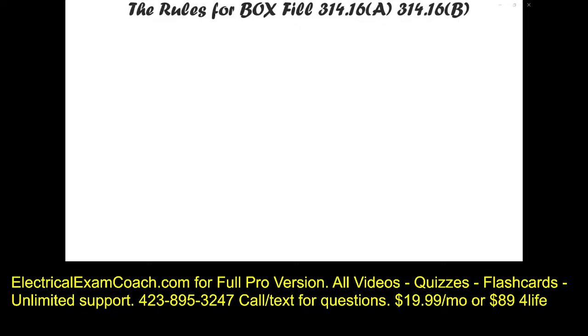We're going to learn how to count conductors now for our box fill calculations. We have to accommodate for each wire and then also for the different devices and fittings that we use out in the field. We're not going to be dealing with equipment grounding conductors at first. We're going to calculate those separately at the end of this slide. So now we're dealing with only neutrals and hots. Each conductor counts as 1 of whatever gauge it is. So each 12 counts as 1. Each 10 counts as 1, whatever gauge wire it is.